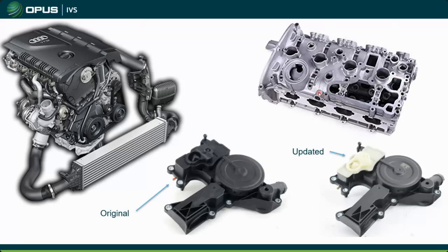We have the cam cradle, which is sort of part of the head, your cam journals here. Obviously, this head doesn't have any camshafts in it, but it's a very integral part. And so instead of having a valve cover, now we have this oil air separator / pressure regulating valve.